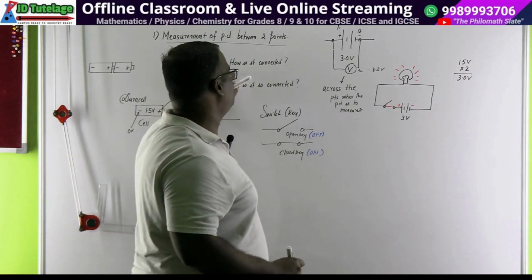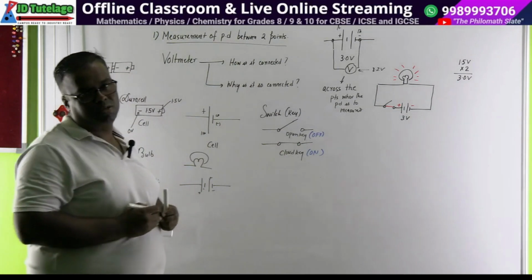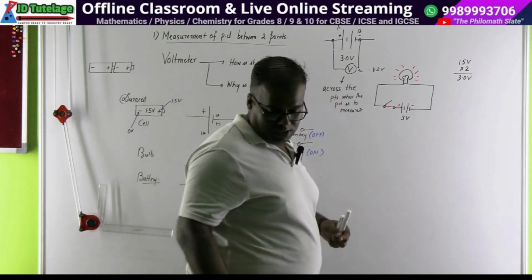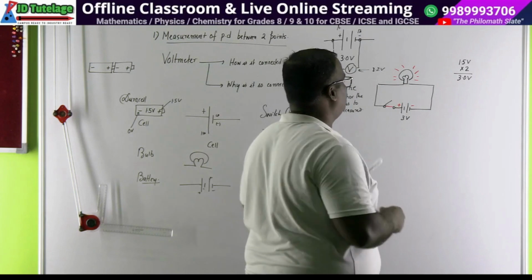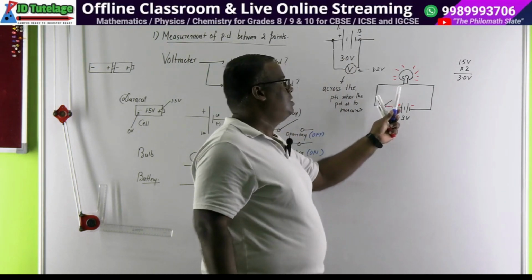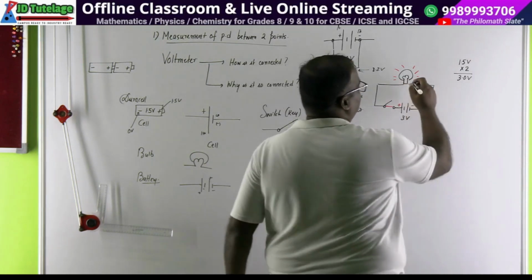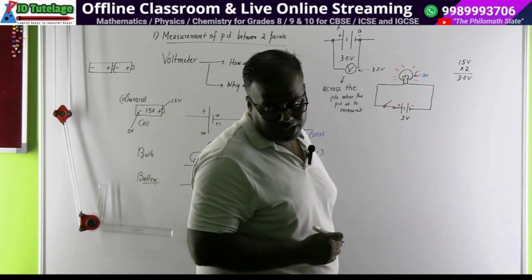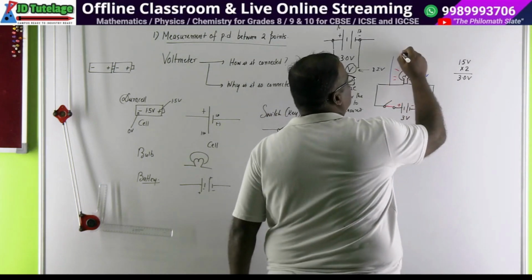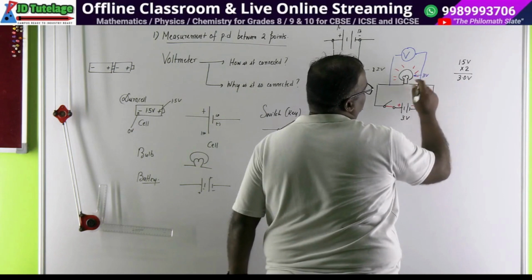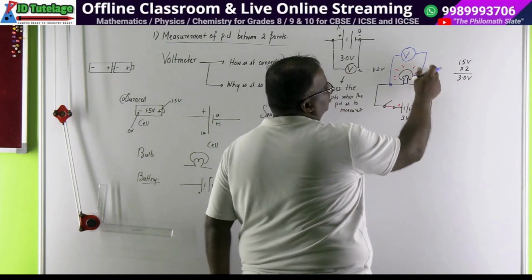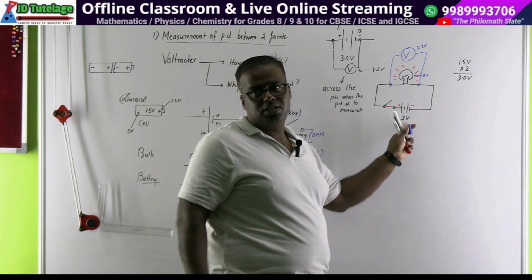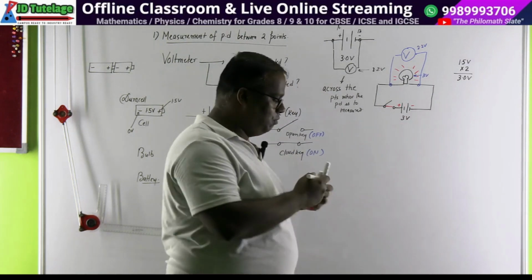So a voltmeter is always connected across the 2 points where the PD is to be measured. Right? So let's connect our voltmeter. Our bulb is not glowing brightly. One of the ways to test it is this way also. Suppose our bulb is glowing dim. Now this bulb needs a voltage of at least 3 volts to glow brightly. So you will immediately connect a voltmeter here across the points. Always remember, across the points means whether the potential difference is 3 or not. And you find that the potential difference is coming 2.2 volt. So your doubt starts, these batteries are not performing well. Got it?